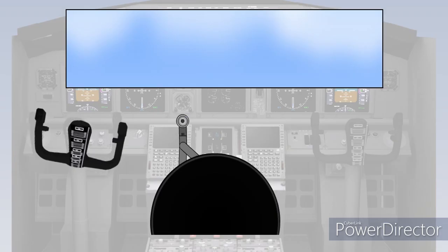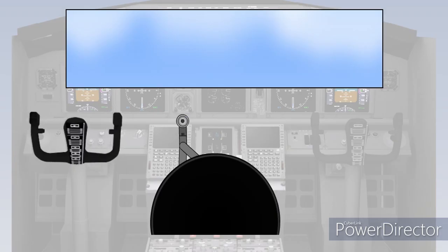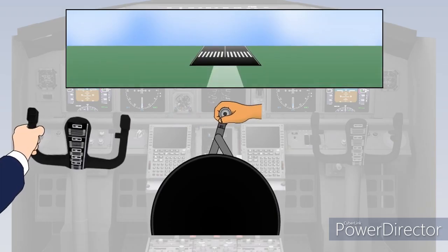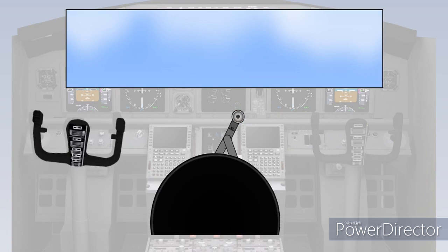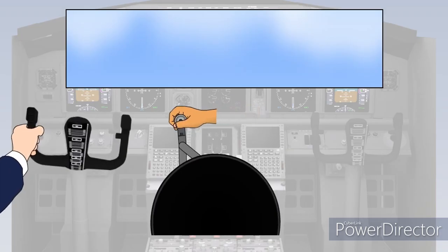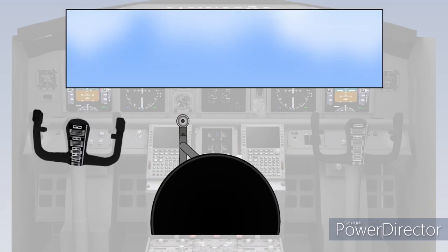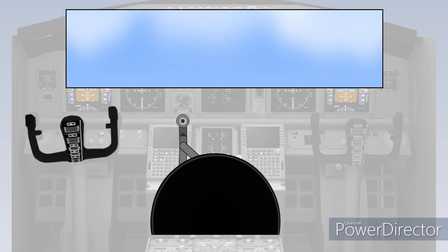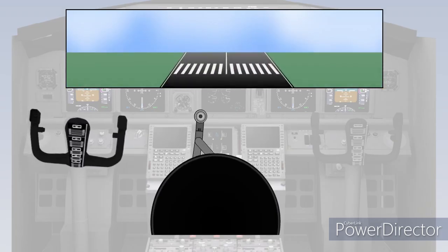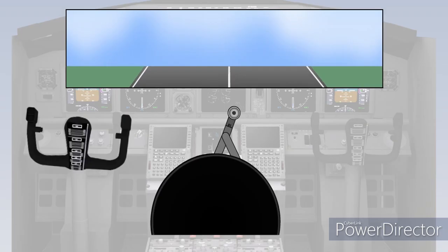Even with the introduction of a single 3-channel autopilot, flying the approach as far as decision height, and assuming the pilot can see the runway, the chances of completing a successful landing vastly improve. However, the limiting factor is still the pilot. If he does not see the runway, he can't land and will have to go around. With a full Autoland system available on the aeroplane, and the required facilities at the arrival airfield, the autopilot system can carry out a landing with 0 visibility and total cloud cover.